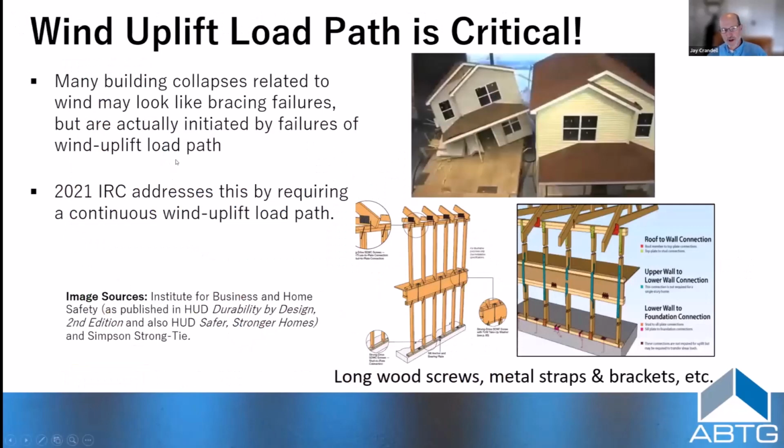Before we talk about bracing in detail, I've been to a lot of hurricane and earthquake events, but particularly hurricane events and some tornado events, and done scientific random sampling of buildings, documentation of performance. And probably the biggest failure you see is wind uplift. Rarely is there a bracing failure unless there's major non-compliances with very little or no bracing, same in seismic events. But for wind, it's the uplift that gets you.